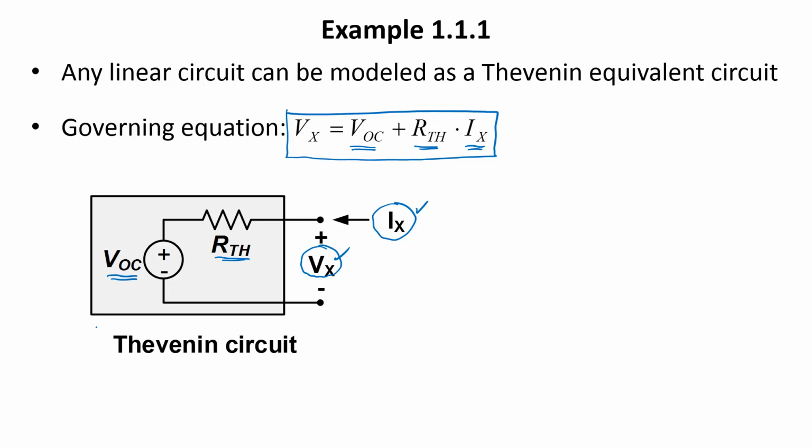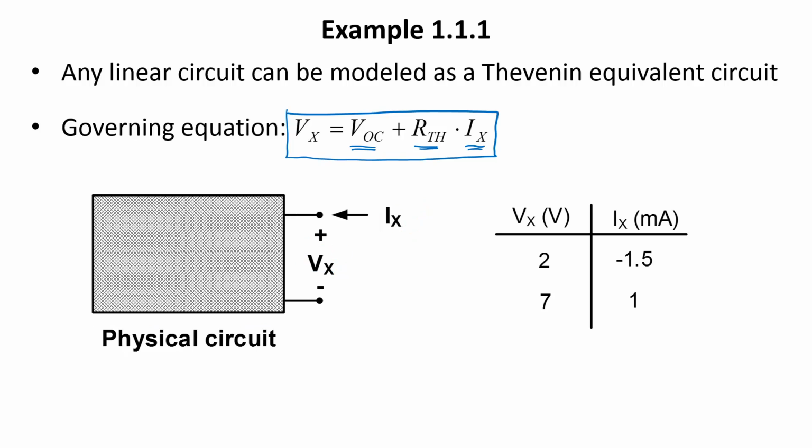Keep in mind that this Thevenin circuit is not the actual physical circuit. The actual circuit can be very complicated, but the Thevenin circuit is, for analysis and design purposes, identical to the actual circuit, but it's much easier to work with. One really nice thing about Thevenin's theorem is that you can determine VOC and RTH from measured data.